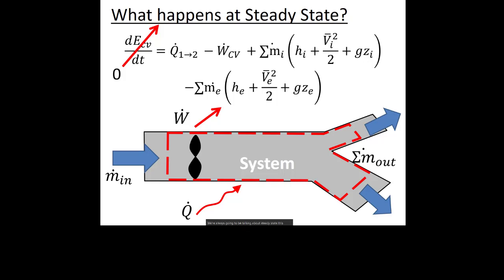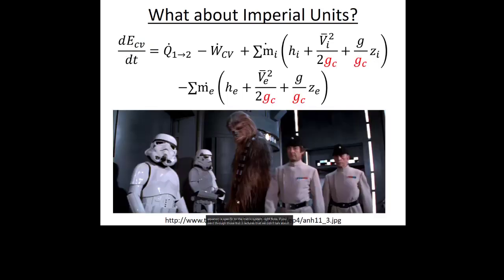Now, if you went through those first 3 lectures that we didn't talk about in class, you notice that it starts to talk about things like weight versus mass, and how that always gets a little bit messed up in the imperial system because you have pounds force and you have pounds mass. In some mechanical engineering classes, we get around this issue by talking about slugs, right? Where slugs is like an imperial unit of mass that's equivalent to kilograms. And then you can use Newton's second law to say that the slugs times the acceleration in feet per second is equal to a force.